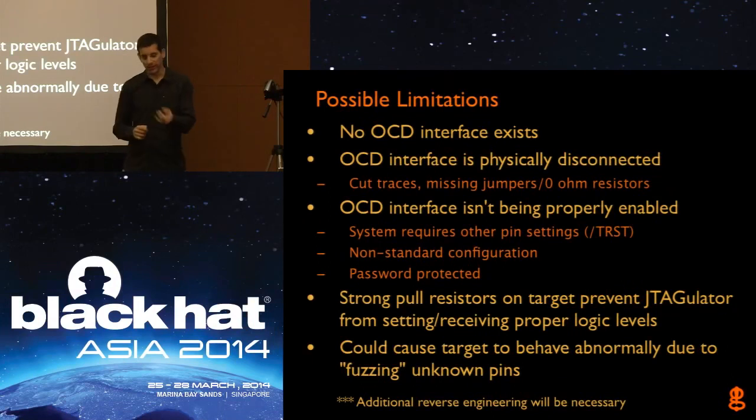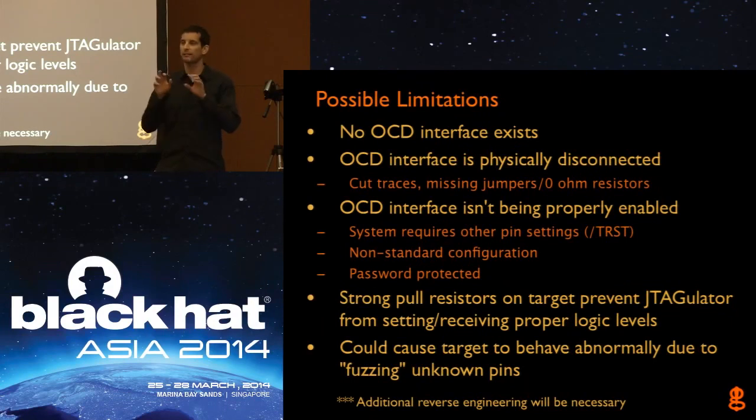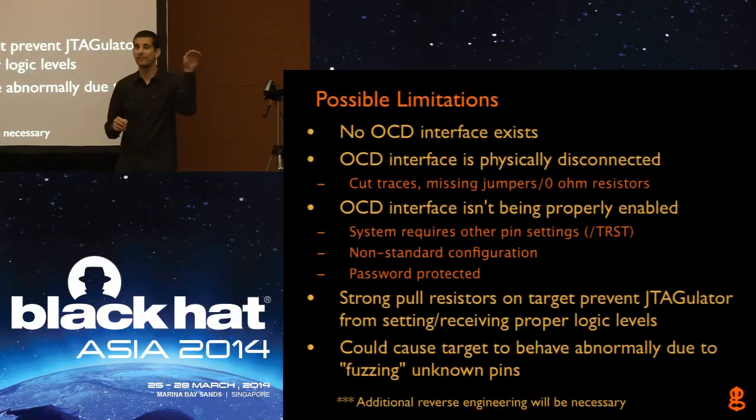What we have right now with the current firmware that's available on GitHub and that's on the units, any pin or channel we're not currently manipulating, I have set high. So if there is a reset pin, it's going to keep it high, so it's going to enable it.